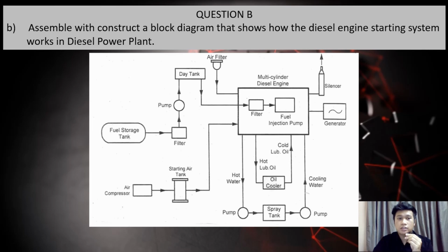For the air filter and supercharger, the air filter is used to remove dust from the air taken in by the engine. An air filter may be of the dry type, which is made of felt, wool or cloth. In bath oil type filters, the air is swept over a bath of oil so that dust particles get coated. The function of the supercharger is to increase the pressure of the air supply to the engine, and thereby the power of the engine is increased.